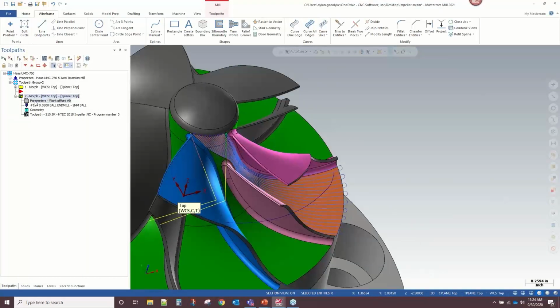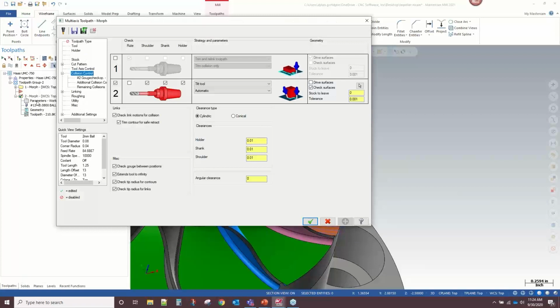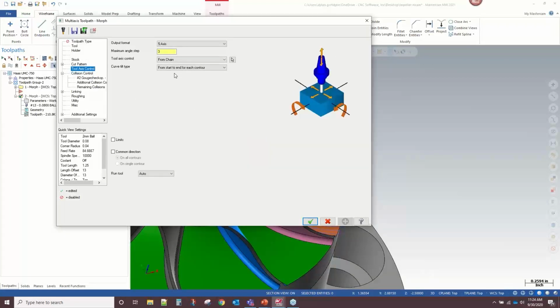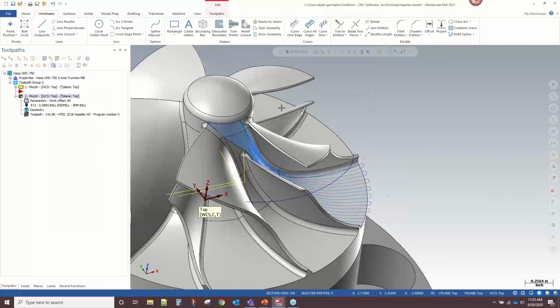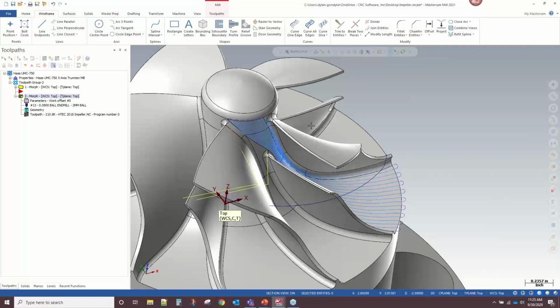So the core concepts here are, I baked in my good motion, my pure motion, right into the tool axis control. So I'm explicitly telling MasterCam what I want out of that tool pointing before I ever have to modify or change it up with a collision control strategy. So that results in a super, super clean toolpath, and it's easy to envision what the end result is going to be because you're not feeding all this motion into a black box that's going to make radical changes. This is just making the small final tweaks to this path to get it perfect. And that's kind of the core concept behind using this simple wireframe geometry on shapes like this.